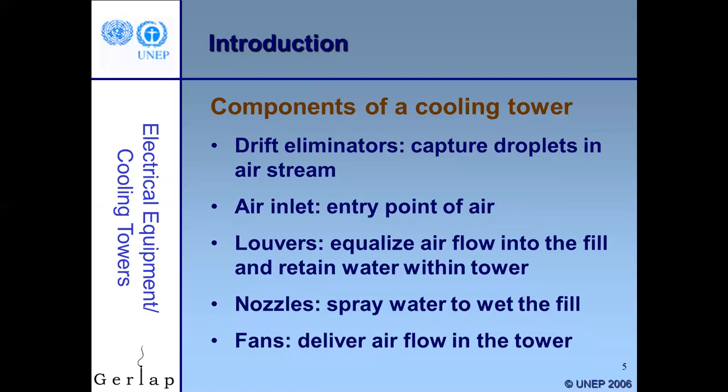Okay, additional components, drift eliminators. After the air comes out of the fill and is traveling usually vertically up through the tower, someplace along the way, it can be right at the exit of the fill, or it can be further up in the tower, they have these. They're really kind of like louvers that go back and forth, and hopefully as the air with the droplets flows through them, the droplets will impinge on these louvers, and then they will stay in the tower. They will drop out of the airstream. They're pretty effective, so that's just a mature technology.